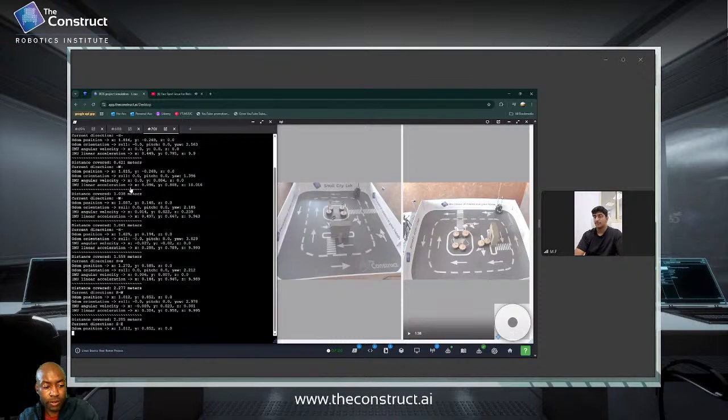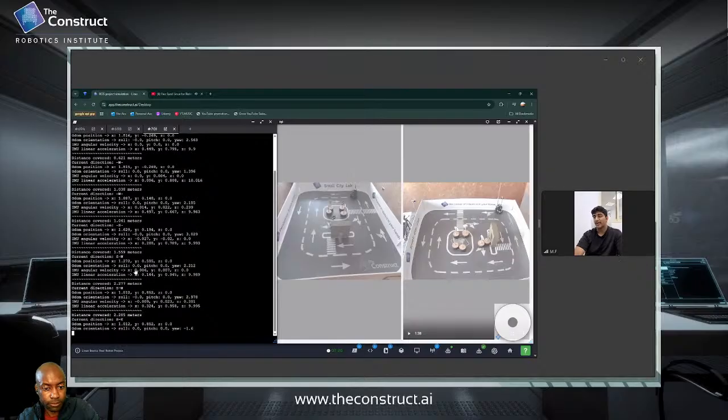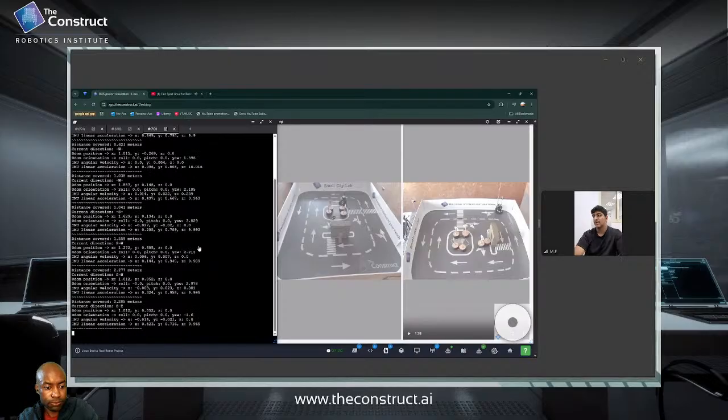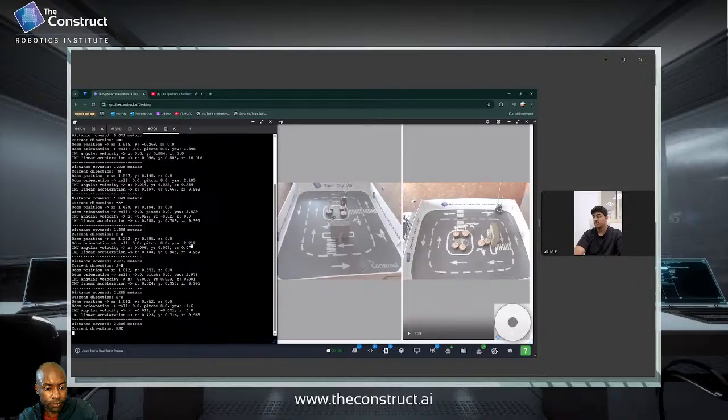Okay. So we get things like the odometer position of X, Y, and Z. We see the orientation: the roll, the pitch, the yaw. Roll and pitch shouldn't really be affected at all because you're basically going on a flat planar surface, so there shouldn't be any change in that. If anything, it should be only yaw, because you're just moving on a single axis in turning point.